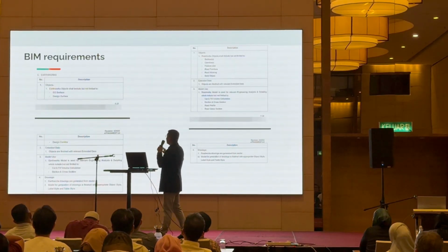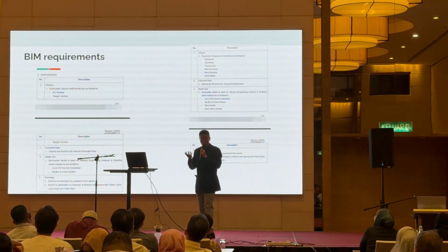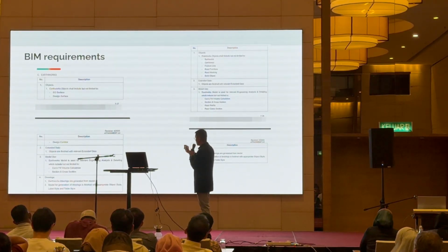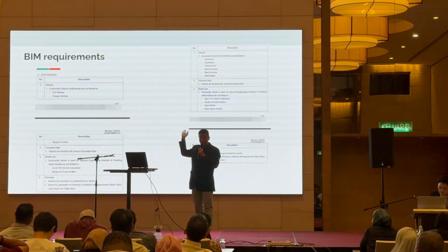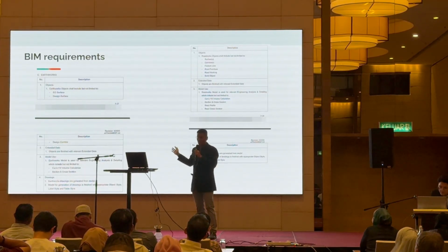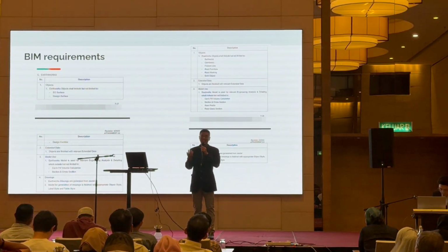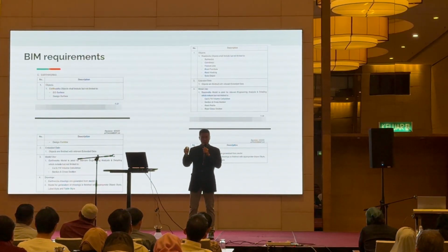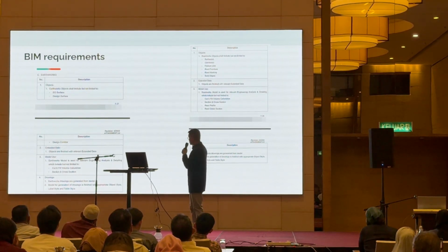Now let's recap again. This BIM requirement: all the surfaces as you saw just now, we can generate surfaces in Civil 3D. And then we can generate all these object styles, label styles, and table styles, like what I showed you just now. In the sneak peek part, you can see all these label styles and table styles, and this is exactly what this document means. So basically, the JKR BIM is heavily latching on Civil 3D terminology and vocabulary. And now we want to give it all to you. For that, we just want to generate everything for you through these commands.